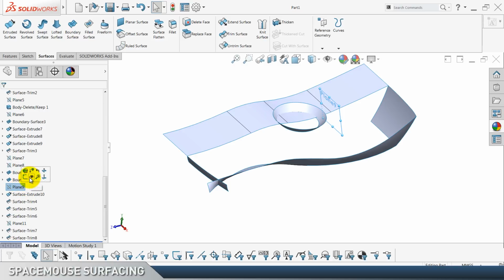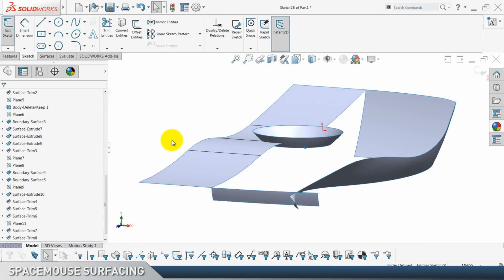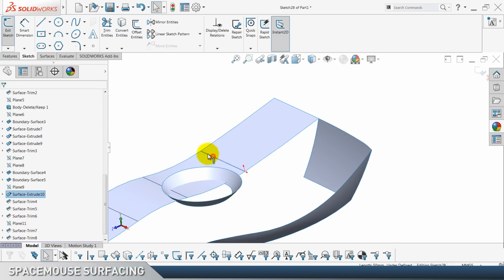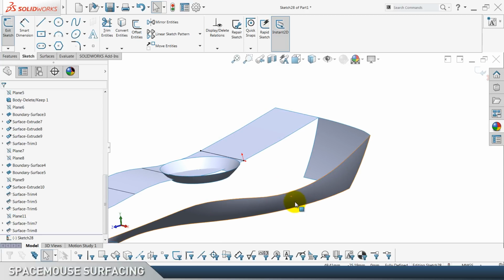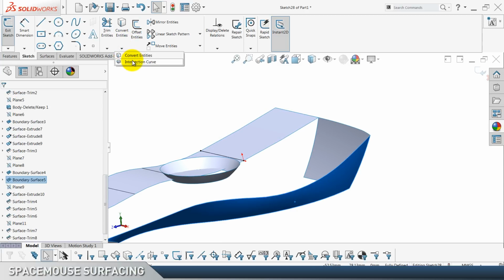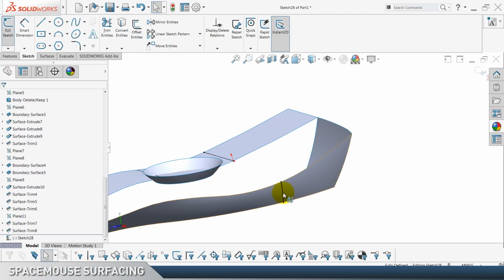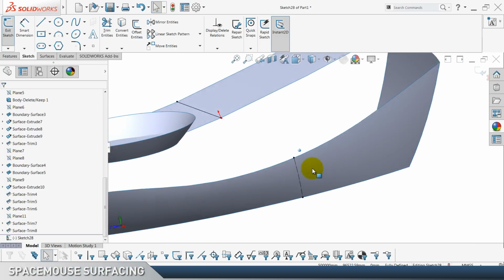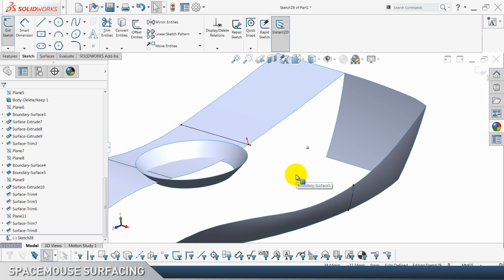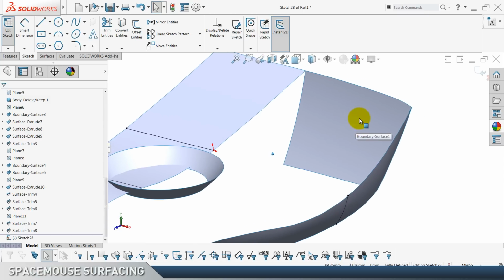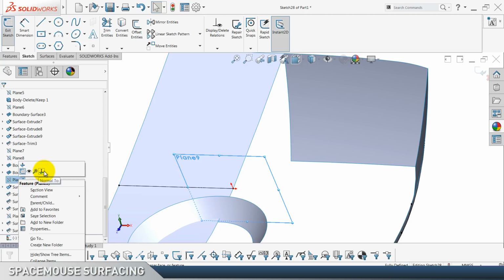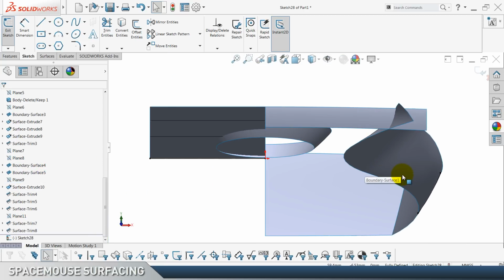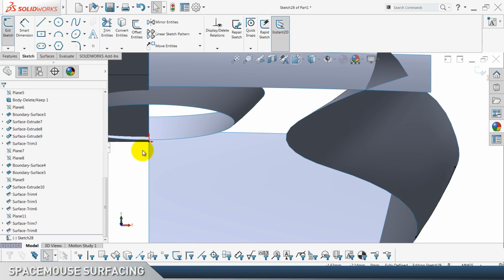Next thing is the plane. This one, sketch. I'm gonna rotate, convert this one, make it for construction, and I'm gonna select this face and go to intersection curve. Intersection curve is something like converting the face in the plane where we are drawing. So we need something similar to this previous sketch. So I'm gonna bring back this view, normal tool. It's not easy to see, but it's visible.